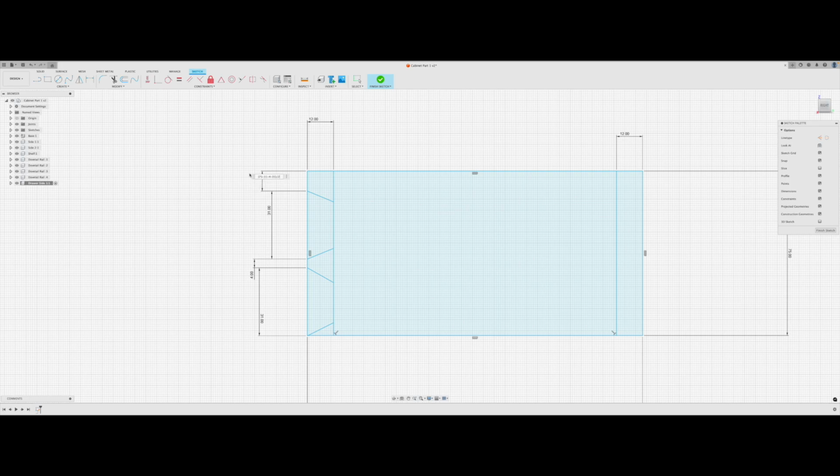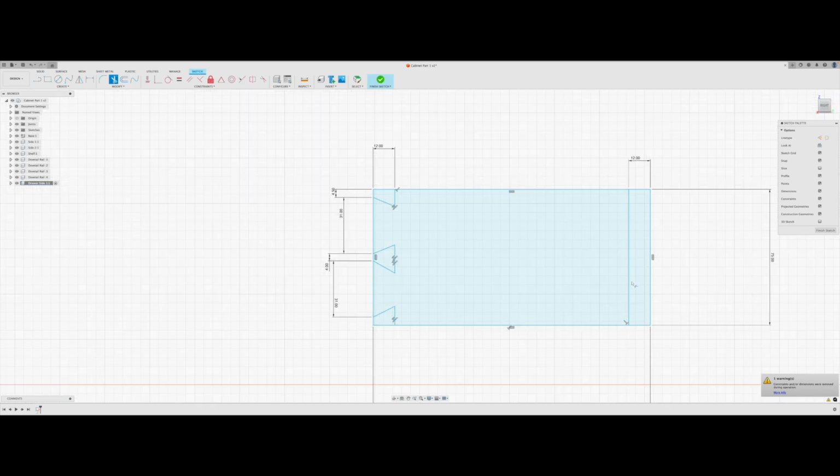So just remember you'll need your brackets for order of operations. So the answer is 4.5, and there it is sitting exactly in the middle. So that end is now done. The last thing I would do though is just trim that line and that line using the trim tool so you can easily see your piece of wood. Now we'll come back in a minute and we're going to fix up all these dovetail angles because they're all slightly different because we just drew them.